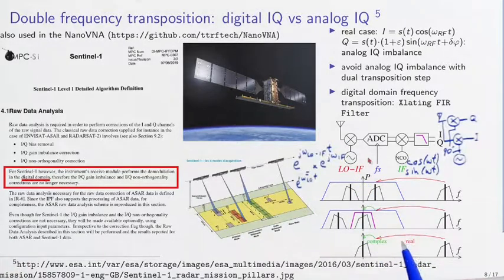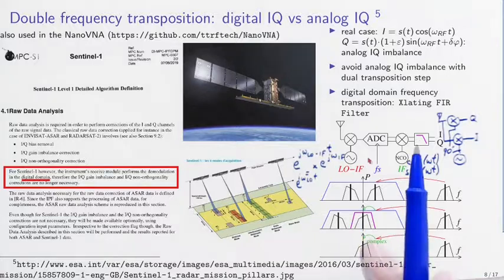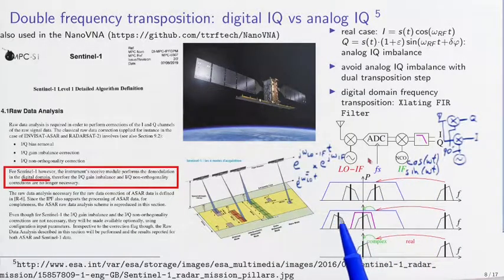So this is illustrated over here by mixing this A to D output with the IF frequency of this numerically controlled oscillator. We take both spectral components, bringing this spectral component centered on 0. This spectral component, if the sampling frequency is wide enough, is only shifted away from the center frequency. And by taking this low-pass filter here in purple, we get rid of the image and we only keep the original signal.